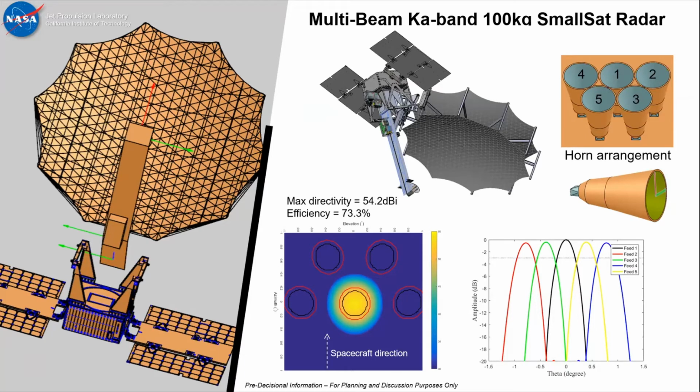And with this design, we haven't built this antenna and tested it, but we're very confident because, as you could see on the two other designs, we were always spot on with the prediction. So we think that we can achieve more than 70% efficiency at K-band with each of these horns at K-band, 35.75 gigahertz.